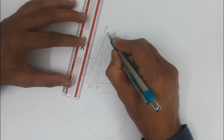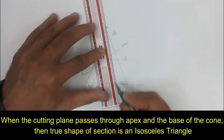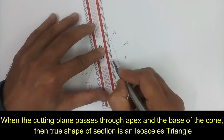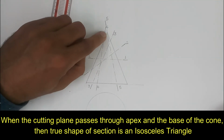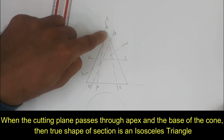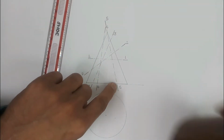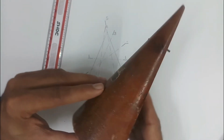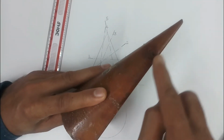Make the cutting plane pass through the apex and cut the base. In this case we are going to get one corner which contains the apex and there will be two more points at the base. Here I have that particular demonstration. The cutting plane passes through the apex and it cuts the base.